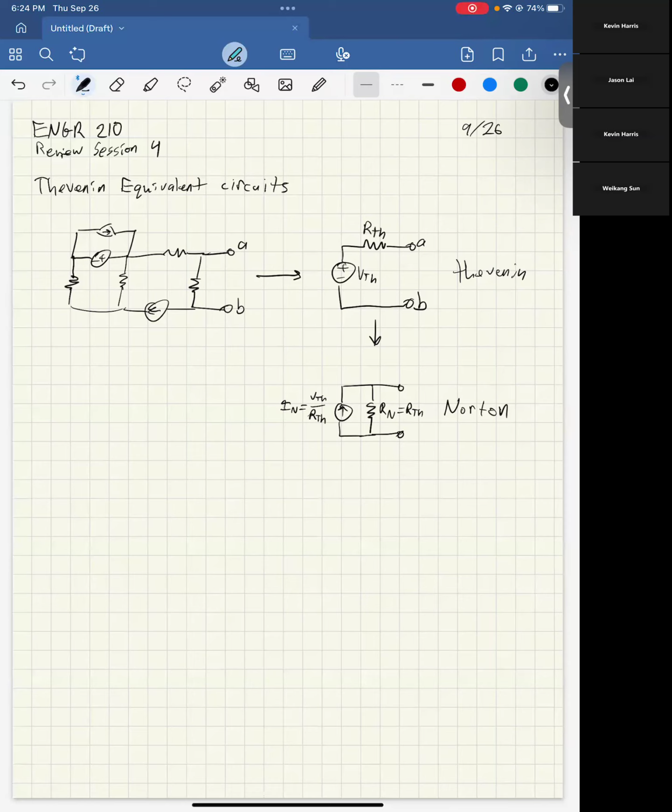And then moving on, the next thing you learned is maximum power transfer. The idea there goes back to the Thevenin equivalence. If I have a circuit like this, with some resistor, and to the left of here is my power supply, and it has some voltage it's supplying and some internal resistance, then we want to figure out the maximum power that can be transferred to this resistor.